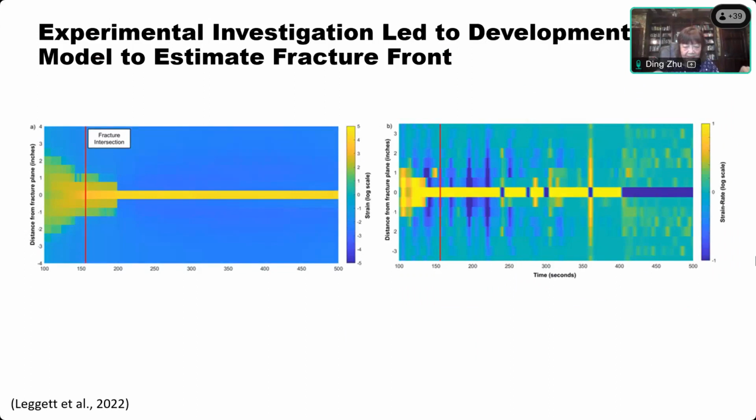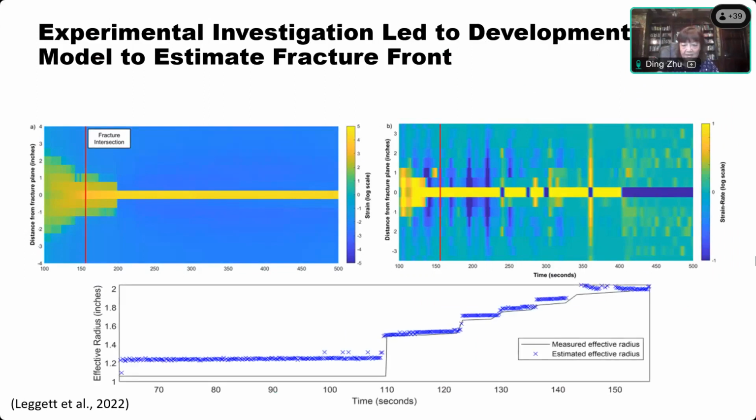And I also can identify the frac hit location. And this also actually tells us I don't have to wait until the frac hits me. I actually can see this cone pattern approaching my parent well. So in reality, if you really want to stop one of those, I can see the fracture coming maybe about 100 feet away. You actually can change your operating situation in real life to maybe lower the flow rate, maybe skip a stage.